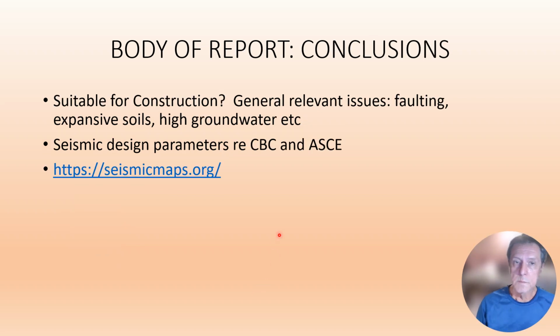Conclusions in your report. Is this site suitable for the type of construction that the client wants to construct? General relevant issues again. You want to include a statement in your report that says, yes, this is suitable for construction. If it's not, then you have to say that too. Or you can say, this is suitable for construction if you follow our recommendations, which most geotechnical and engineering geology reports actually say.